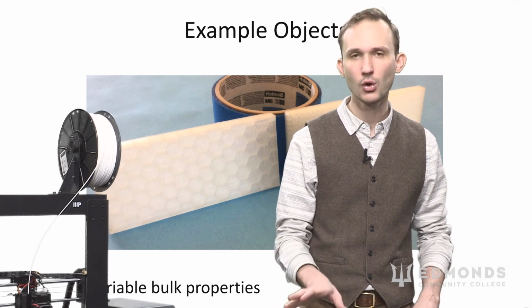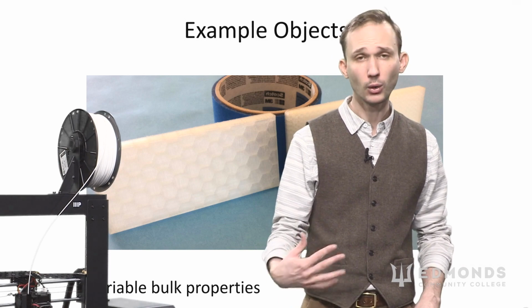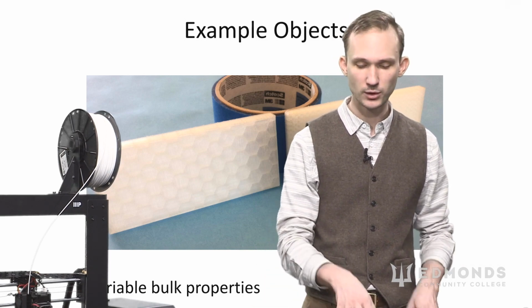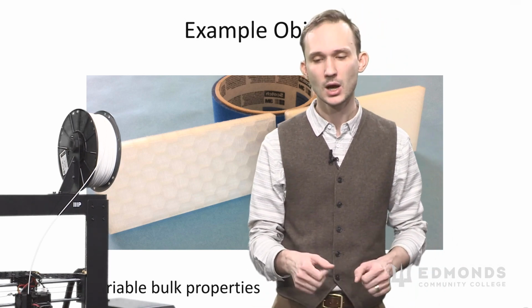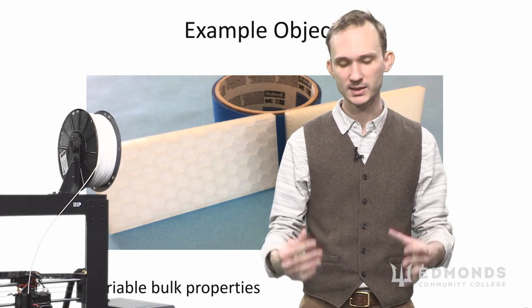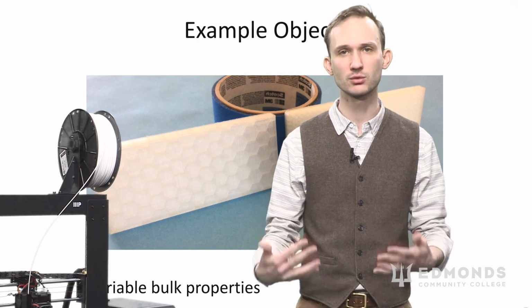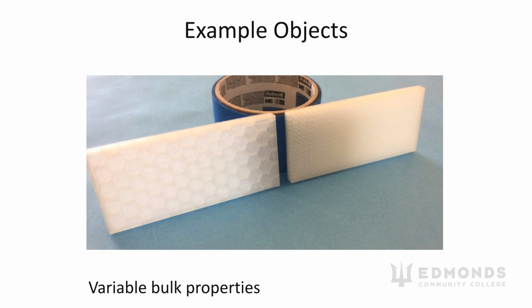So we want that low modulus so that the bone in the patient that's interacting with our titanium 3D printed part doesn't stop growing, because that bone continues to experience stress. And the titanium part, which is now more flexible because of its low infill and therefore its low modulus, remains flexible, the bone continues to grow, and the patient doesn't suffer from osteoporosis, for example.